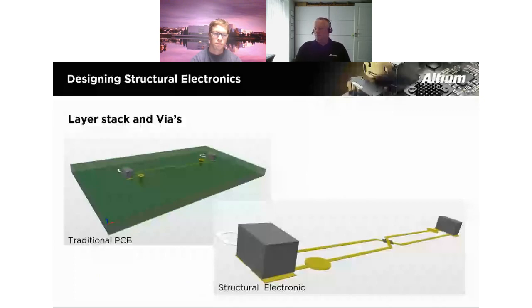The traditional PCB uses a layer-oriented fabrication technology. This is a reductive process. So each conductive layer starts as a continuous sheet of conductive material, such as copper, for instance. This is then etched away, leaving only the copper that performs the required conductive pathway here. Now, it is also a multi-stage process, as the individual conductive layers are sandwiched together with alternating layers of isolation and various drills and post-plating process applied for vias